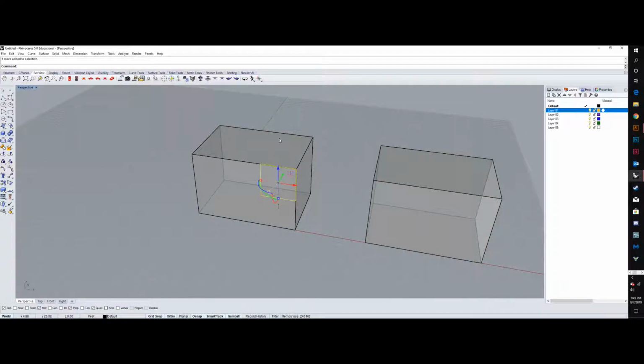I'm going to do it in the Y direction, where I'm going to extrude this. Extrude surface, SRF, all one word, enter. That's actually the wrong command. We'll do Extrude Curve. See, there's a very big difference there. It won't do an extrude surface if you don't have a surface to select. So you need to do Extrude Curve in this instance. Select the curve that you want to extrude. Now it says select to extrude, so it's still wanting me to select curves. We already have the curve we want, so I'm going to right click or push enter, same thing.